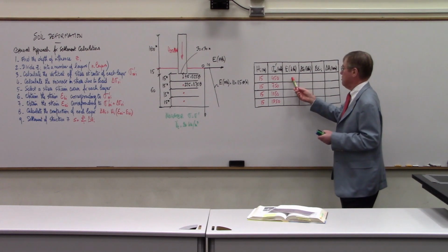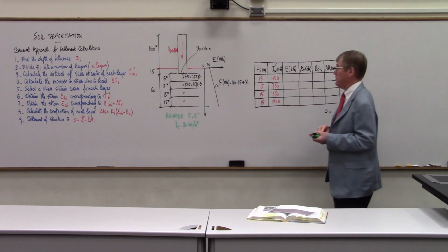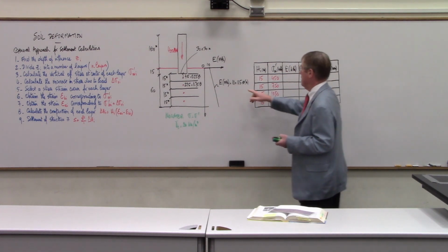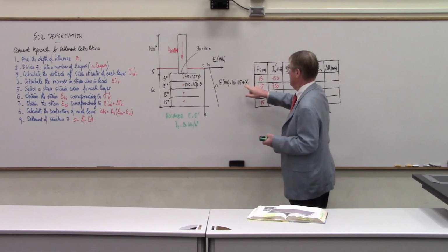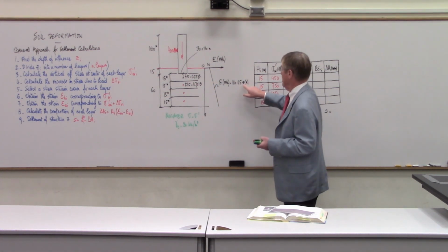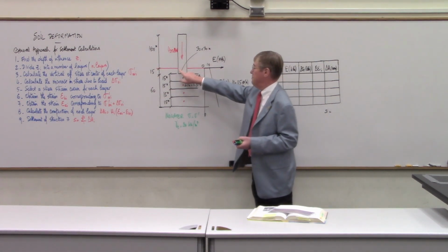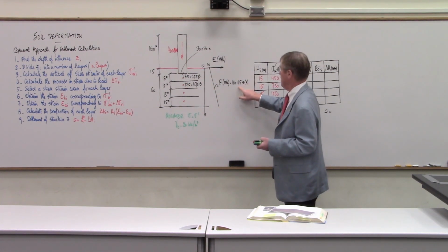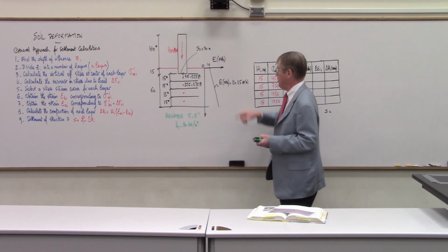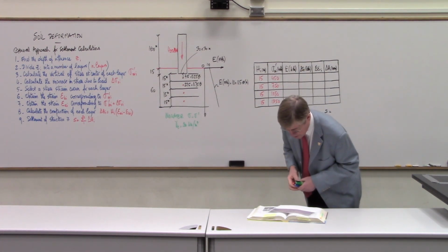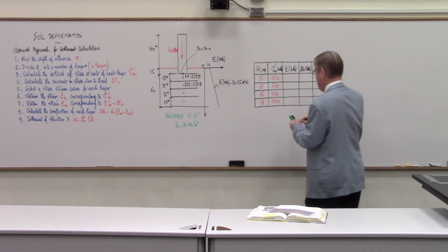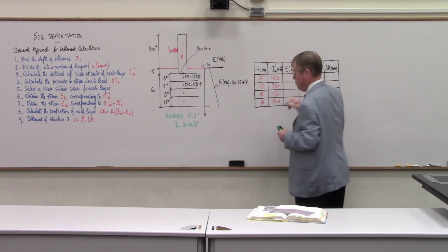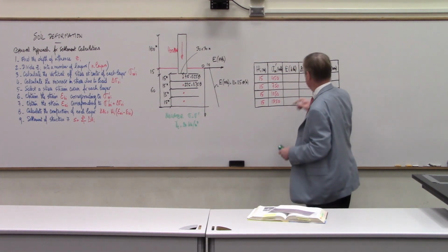Then we have to calculate the modulus at the center of each layer. We have this equation for the modulus. So we go back in the center of the first layer, and the depth is 15 plus 7.5, 22.5. So 1/2 of 22.5 plus 10, and that gave me 21,250. Because this is megapascal, but I need it in kilopascal here to be consistent.